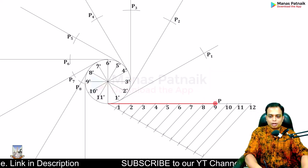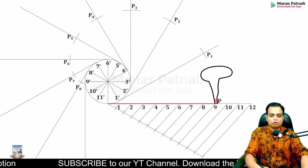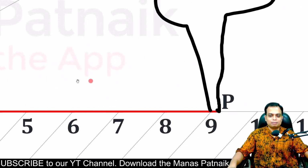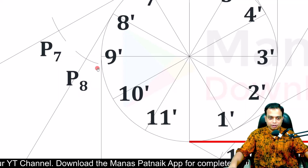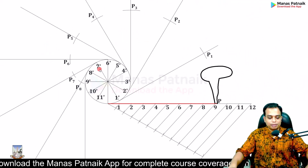And now the final point, 9 to P, is going to be extremely small. If you want, I can zoom in. Here we go. Extremely small. And from 9 to P, with 9 dash as the center, you need to cut an arc. This is extremely small. That is going to give you P9.